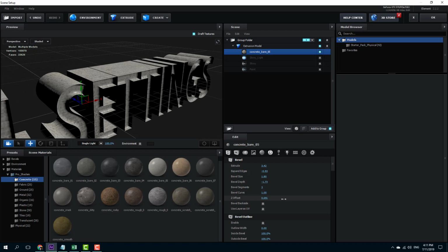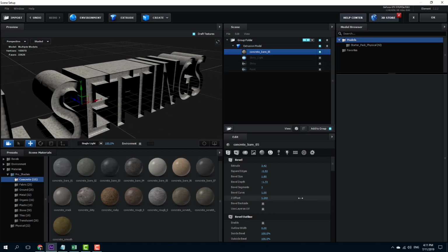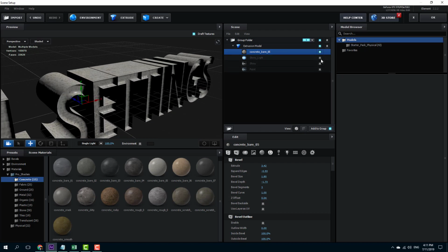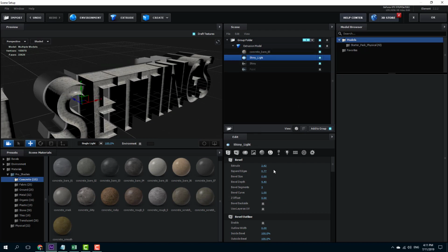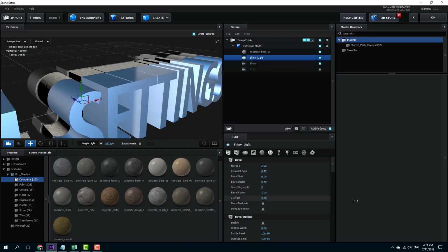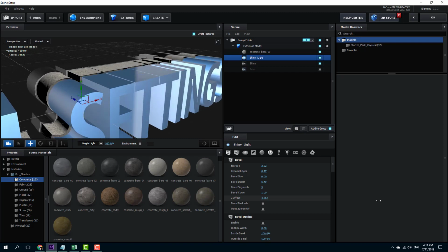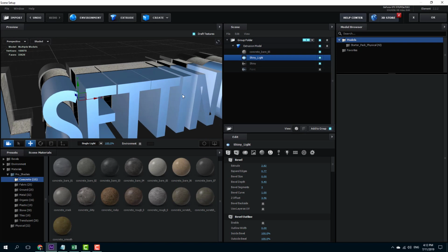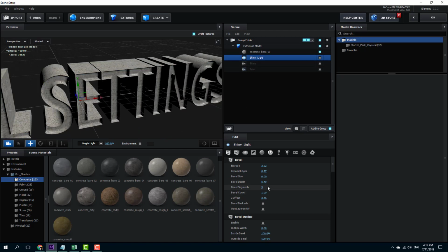All right, there's also the offset. That is simply the offset of the bevel, and this actually works with multiple bevels on. If I go to offset right here, you can see that it works around with the different objects just like that. There are 3 bevels right here and the offset actually changes the distance. Let me disable this one now. And that is how you can work with bevel settings inside of Element 3D.